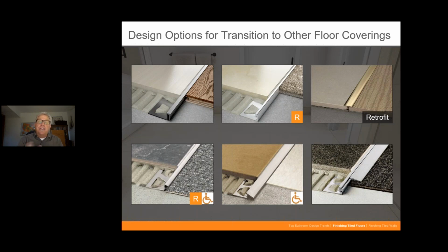The next one over in the center on the bottom, again, that can also be used there for ADA transitions. We do make a couple that don't meet ADA, so make certain you read up on the Americans with Disabilities Act and transitions and slope ratios. It's going to change as the elevations differ there. When you get greater than a ½ inch, you're going to have to go to a wider ramp. But for these smaller transitions where the height is not more than ½ of an inch, there's many, many profiles